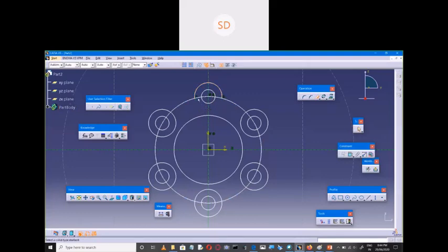Double click. Here someone might ask: you can create this arc and this circle first, then go for rotate as well as instances. That is also okay. If you go for this one, it is going to reduce the time for trimming out the unwanted portion here. Now let us look here. We need to trim this much of portion, right? So that can be saved. Now in a company, they are going to observe all these things, how you are going to reduce the construction time for a particular sketch.